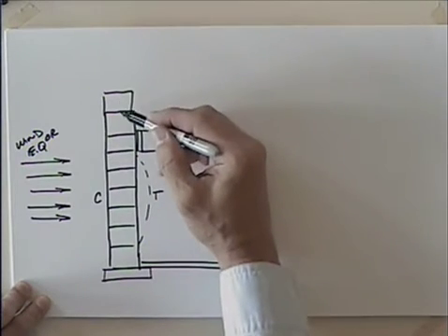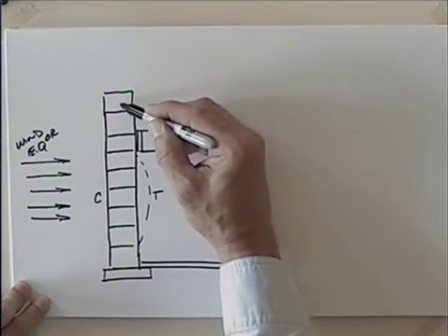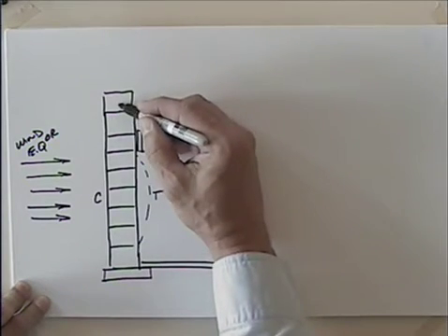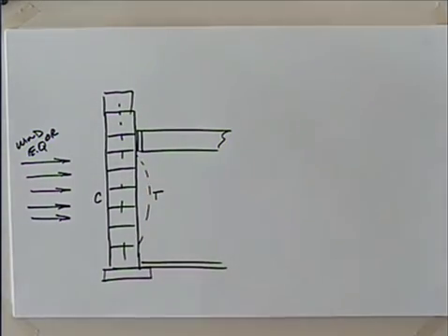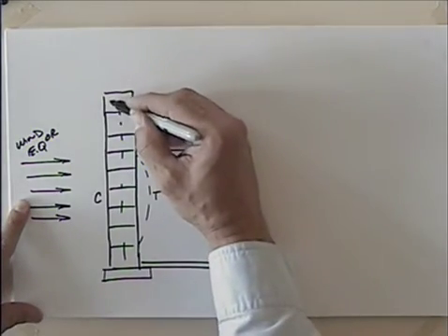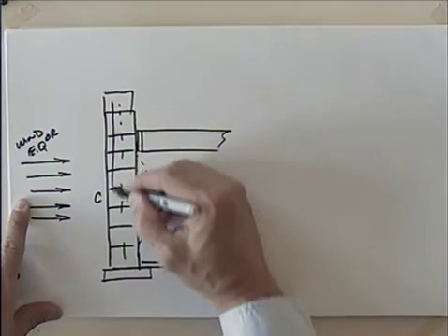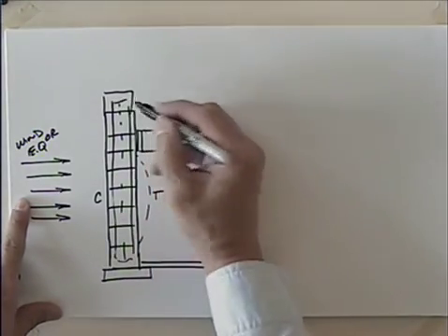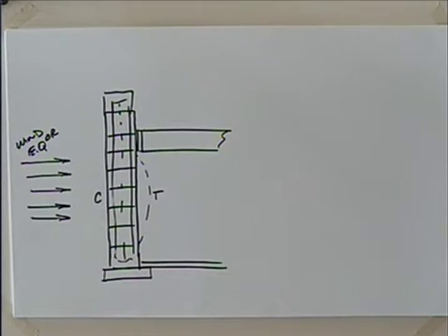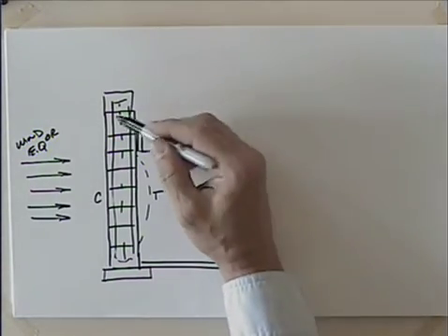And a lot of these masonry structures are hollow. So sometimes what they'll do is maybe you'd go in here and drop a piece of rebar in and fill it up, and that would be one way to do a little seismic retrofit on this. Another way is simply what they call grouting the cells. A lot of the cells were probably left void or empty because that gives you better insulation properties. But if you grout them full, and even if they put some rebar in in the past, they may have only done every other cell or something like that. If it's a prison, then they do all the cells. It's fairly easy to knock a hole in one if it's not grouted. So we fill those all up.